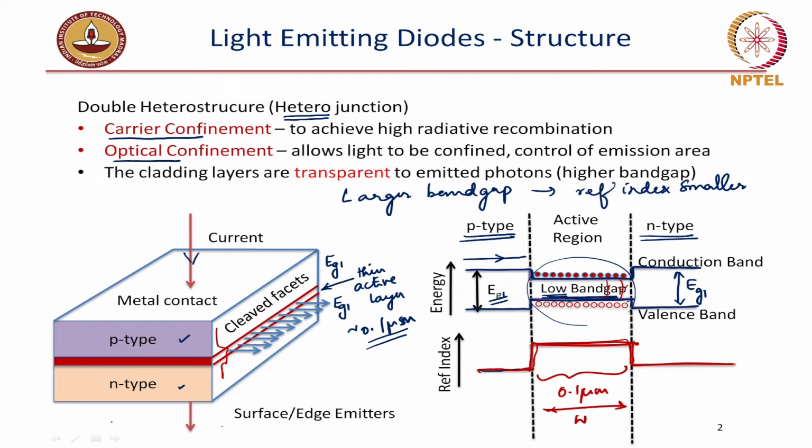So you will have the optical mode which may get confined in this central region, and the optical mode might look like this. Depending on the refractive index contrast and this width, you could have a single mode operation, which means only one transverse mode can be supported by this structure. We will talk more about how to decide whether one mode or more modes are supported later on.